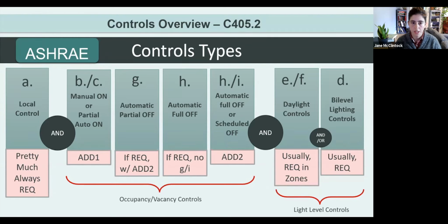I think one of the ways that we might conceptualize the difference from 2016 ASHRAE to 2019 and from 2018 IECC to 2021 is that we're really coming into the LED era. So we're going to have more requirements for things like continuous dimming, more requirements for turning on and off lights, as we're assuming 100% LED, which is a little bit easier to control in those ways.